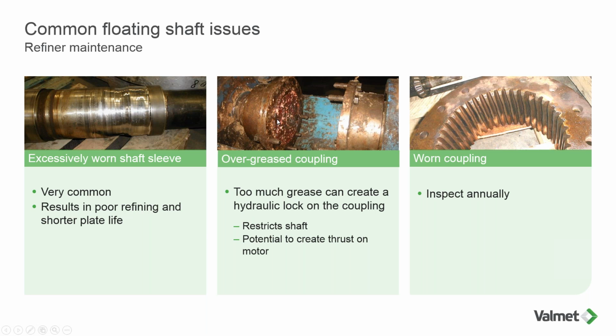If you over grease a coupling, you're going to freeze it in place. So in general, we recommend oiling the main motor coupling, but some customers do decide to grease it, and that's acceptable as long as it's hand packed and not pressed in there such that it freezes in place. And finally, in this traditional floating shaft design, all the movement is happening on this actual main motor coupling.